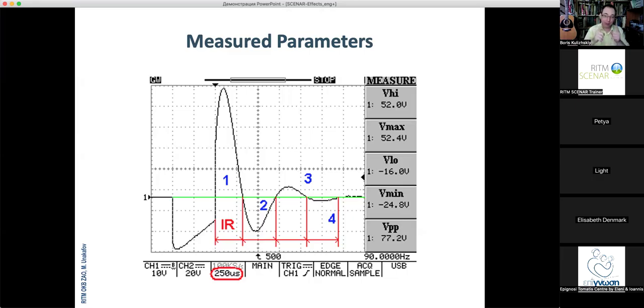If you see a reaction time of 100, the full cycle is 200 microseconds. And this means the scanner device is working with an internal frequency of 5 kilohertz. That's it.